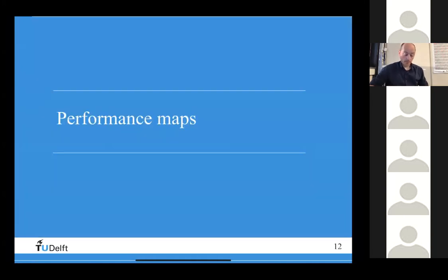And so that's why we have discussed now the performance maps, the ideal performance maps. You're just using one simple mean line analysis, let's say, of velocity triangles of a certain stage, compressor or turbine. And if you do so, we get the ideal performance map.